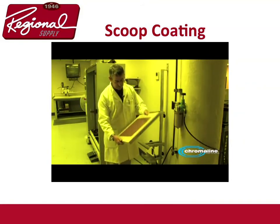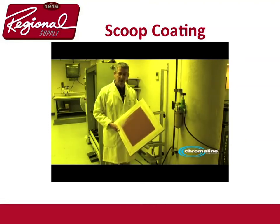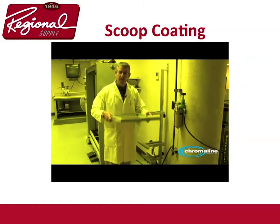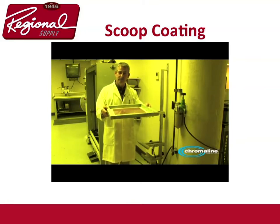As you can see, I have quite a bit of emulsion on this side. The scoop coater has pushed the emulsion through the mesh to the print side. Now, the important thing is that this be dried squeegee side up in your drying cabinet. That's all there is to it. Thank you.